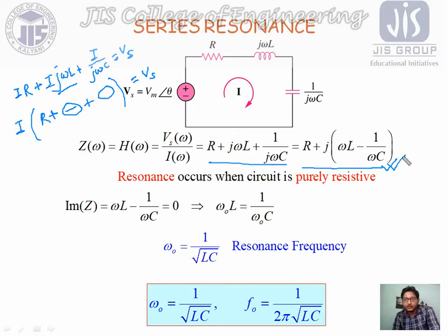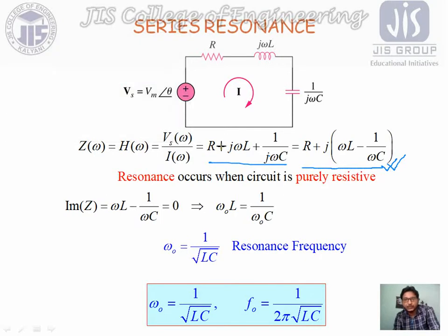Now as you have seen, the resonance condition is when the circuit has the inductor and capacitor with the same effort. It means the inductor and capacitor will nullify each other, so their effect will be neglected. Now let's take an example of what actually happens. As we know, the inductor tries to lag the current, and similarly the capacitor tries to lead the current.